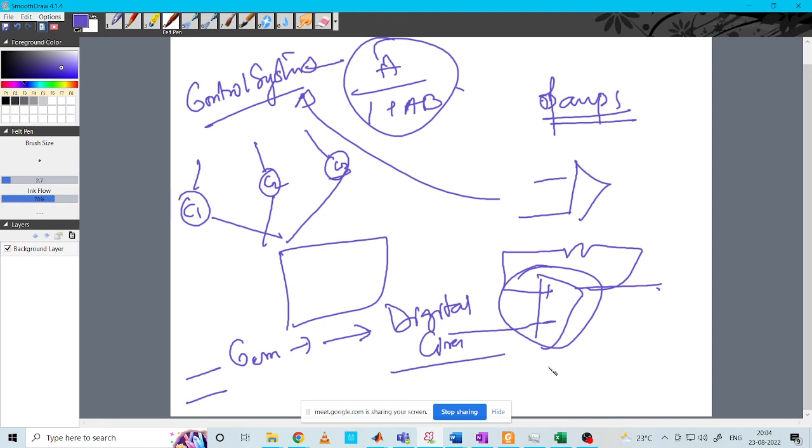Sir, just one thing. In these types of signaling, the voltage levels will be different, right? We cannot say something. Suppose it's from 0 to 5 volt. Maybe the logic high will be from 5 down to around 4.5, and the low will be from 3 to 0. How will be the voltage level for these types of signals in digital?